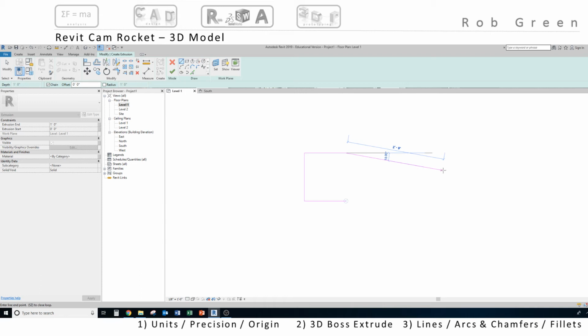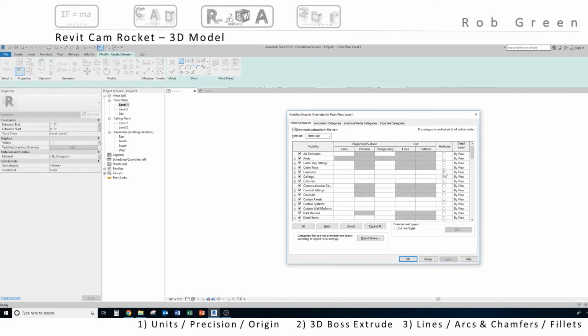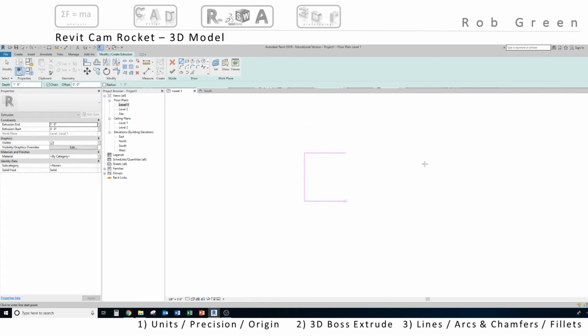Here I know that I want my angle to be 10 degrees, and it's pretty easy for me to just move my mouse to a certain place on the screen, and 10 degrees is the default. So I'm going to do that and just press enter. And I got a result I wasn't expecting. So back to line, come down here 10 degrees and click the second place.